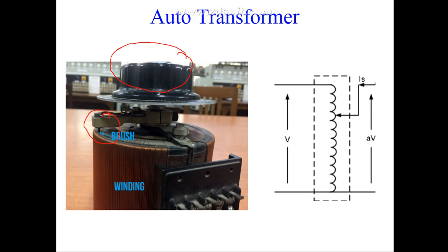If you remember, initially this slider will be here like this, because when you turn on your auto transformer and the marker is on 0, it means it is here, so the voltage is 0, and the output of the auto transformer is also 0. When you move this upside, for example here, it means you are moving in the clockwise direction. Then this slider will move upside and your voltage will start increasing, like 0, 10, 11, 12, 13, 14, and up to where you leave your slider at rest. So you can now change the output voltage of the auto transformer like this.